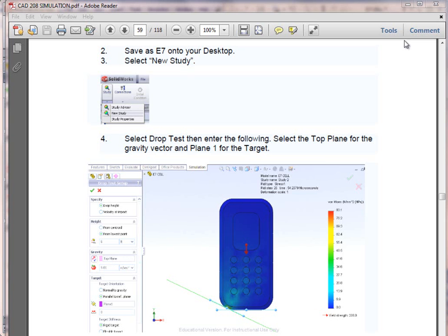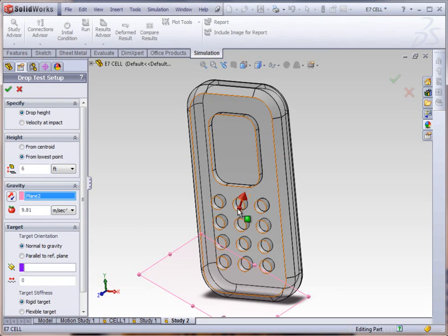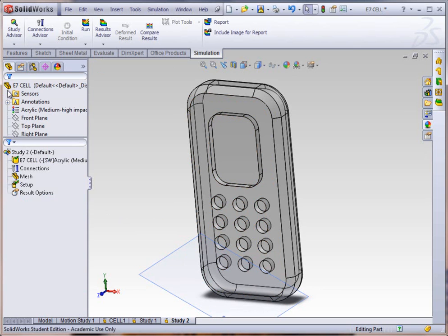With that selected, that will unfortunately make it land flat. So we want to go ahead and, for the gravity here, select this plane. Now you do see an arrow for a direction, it's basically the vector. Go ahead and flip that by clicking on this little icon over here. Hit the green check mark to apply, and now let's go ahead and run the simulation.